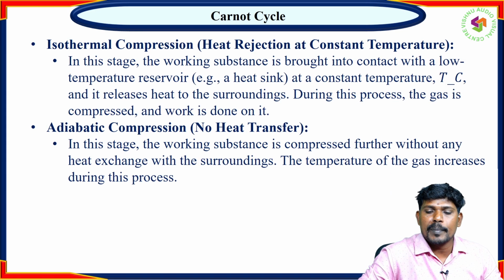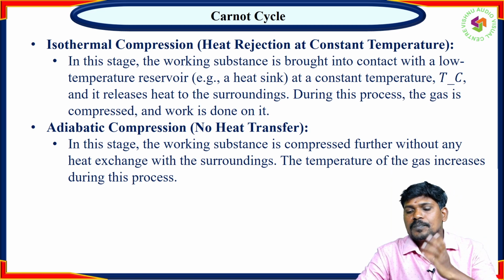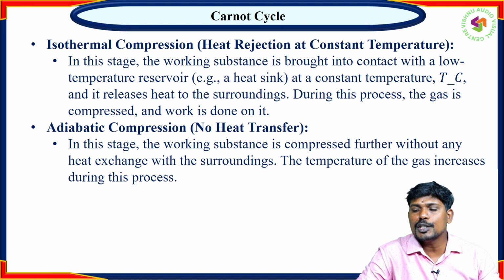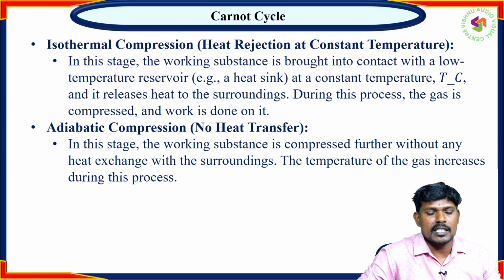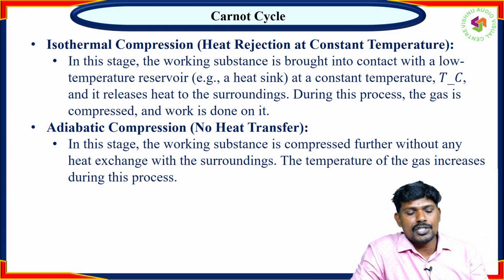Next, isothermal compression: heat rejection at a constant temperature. In this stage, the working substance is brought into contact with a low temperature reservoir, the heat sink. The heat is released at the constant temperature, that is TC, to the surroundings. During this process, the gas is compressed and work is done on it. Next, adiabatic compression, no heat transfer. In this stage, the working substance is compressed further without any heat exchange with the surroundings. The temperature of the gas increases during this process.